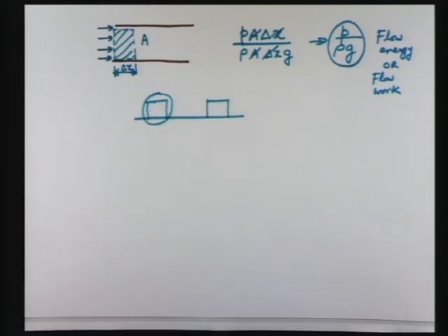So the belt is like a flow field. The flow field is transmitting the energy in such a way that the sum total of kinetic energy, potential energy and flow energy, also called the mechanical energy, is conserved in the absence of any viscous dissipation. This is the physics of the Bernoulli's equation.